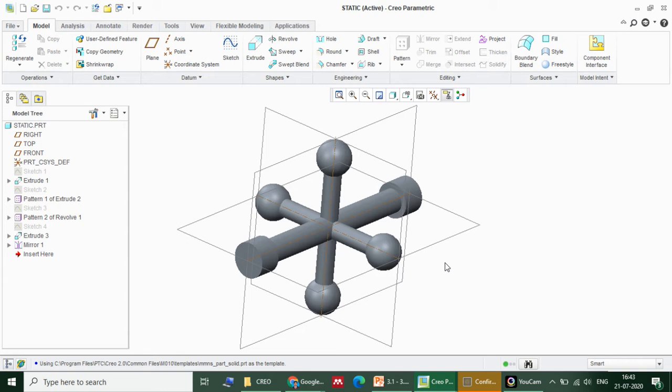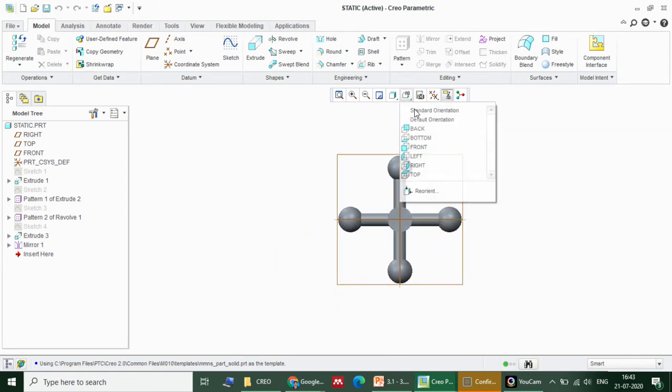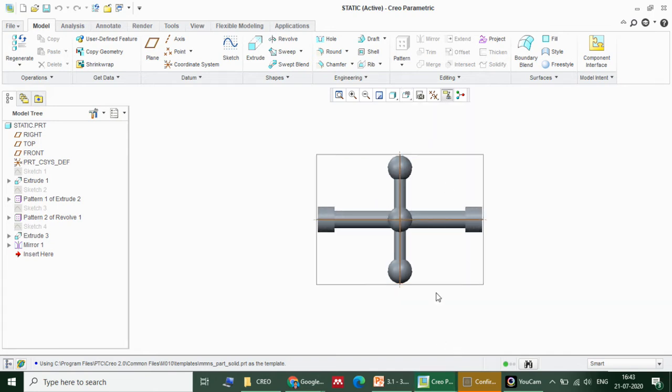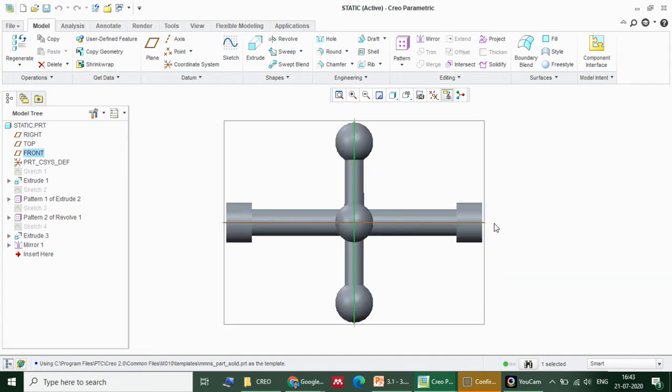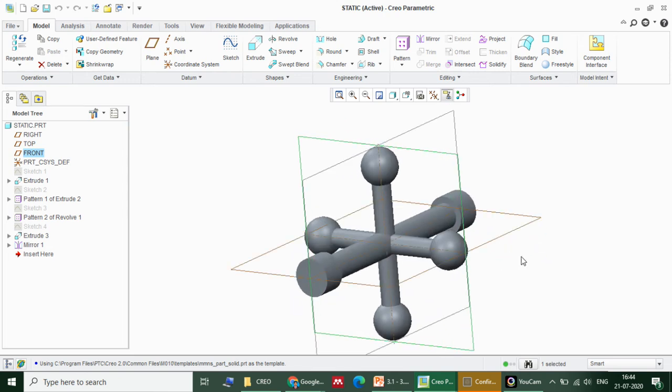Now it happens in case you have the masses concentrated on only one side of the shaft. If the masses are located on only one plane, correct? Can you see the plane? The plane is in green color. All the masses that I have added, let us say three masses were there earlier. I found out the resultant and I have added the fourth mass to balance out. Now it is exactly dynamically balanced. No disturbance occurs in the bearings.